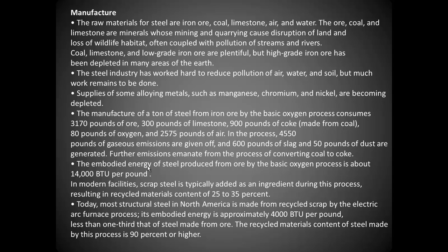It says in modern facilities, scrap steel is typically added as an ingredient during this process, resulting in recycled materials content of 25 to 35%. Most structural steel is made from recycled scrap by the electric arc furnace method, with an embodied energy of about 4,000 BTUs per pound. Less than 1/3 of that of steel made from ore. So there is some energy efficiency in recycling our steel as opposed to creating it from raw materials.